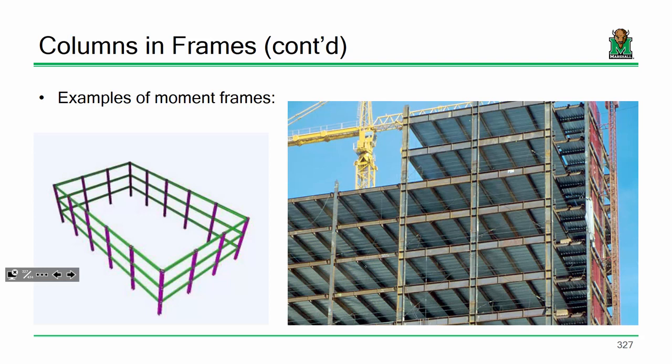Your roofing system. Well, not really, because think about it like this. A building is really just one big cantilevered beam sticking out of the ground, right? Fixed on the bottom. Let's say you've got a 20-story building, right? And you apply load to it. Well, shear and moment diagrams tell me there's really not a lot going on at the roof. See what I mean? I'm not saying it doesn't help. I'm just saying it doesn't really do much. Does that make sense?